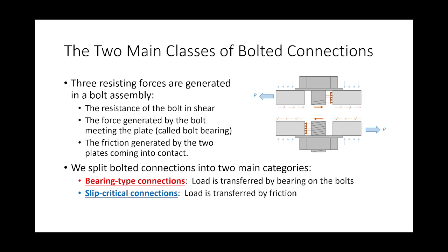Now, if I have a bolt going through a plate and I load, the bolt is actually going to come in contact with the plate, right? Remember, the bolt holes are a little bit larger than the bolt, and so as I load, the bolt is going to come into contact.